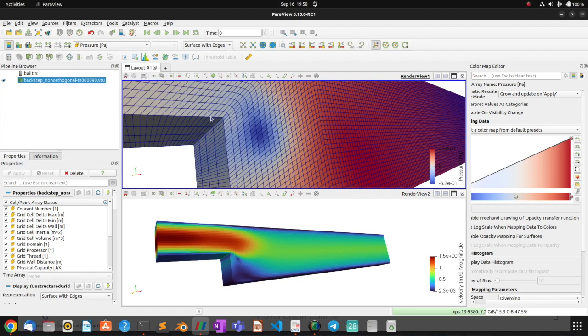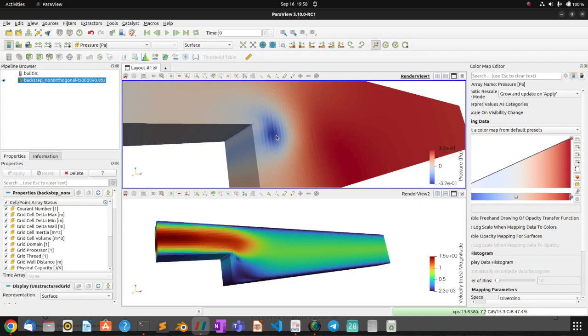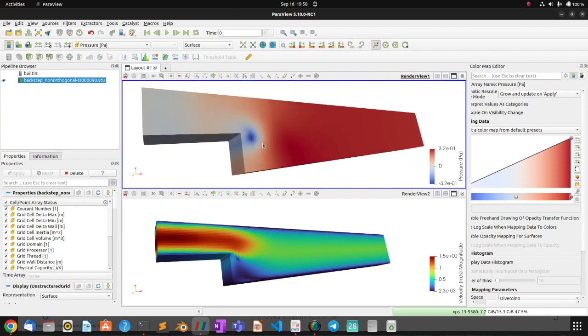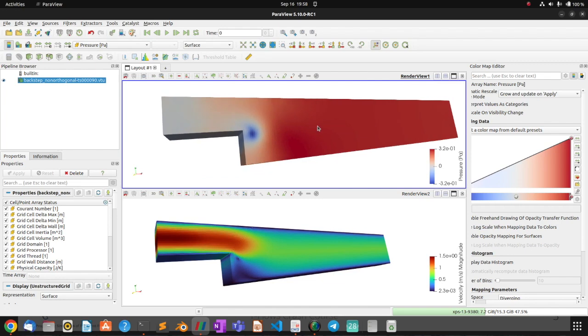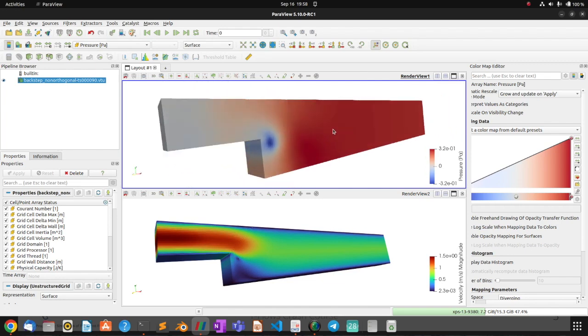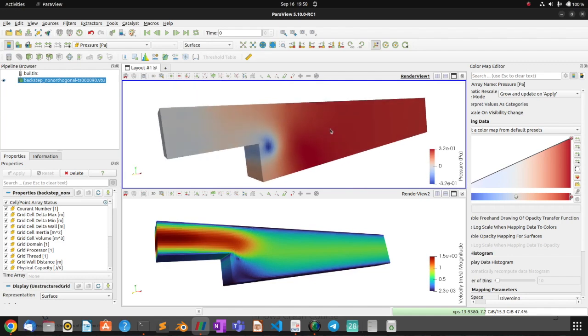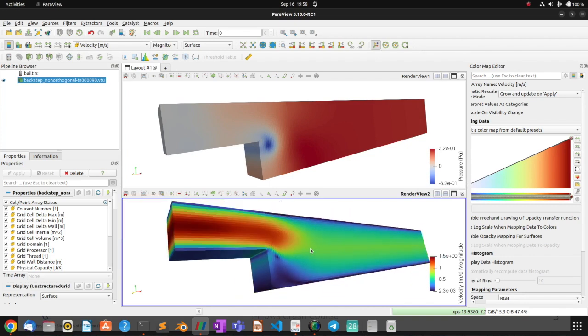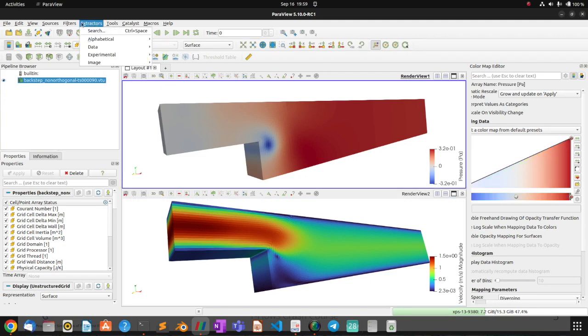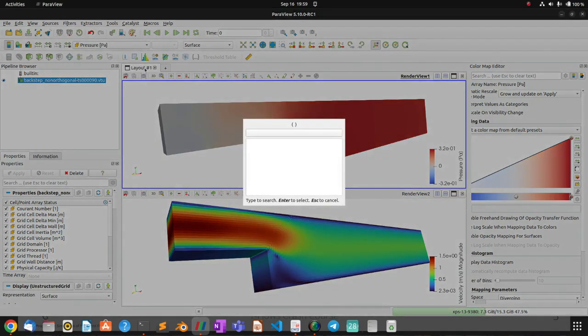If we have a finer mesh, then you have a better resolution, and a much better representation of the flow because you have more details, obviously. But nonetheless, if you want a smoother representation, not the most accurate, but an interpolated picture of the flow that looks a bit smoother than this kinky way, for a scientific paper or a project, then you should use one of the filters, and this one is called cell data to point data.